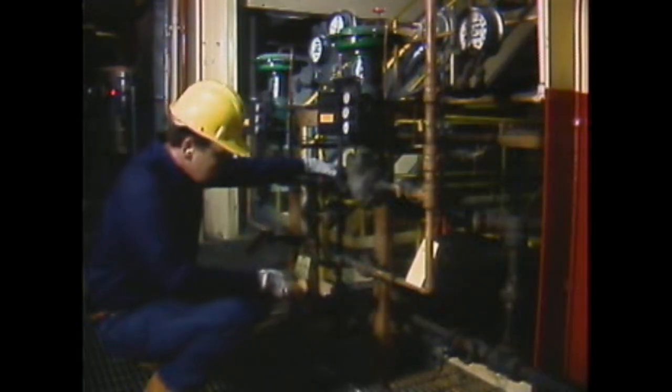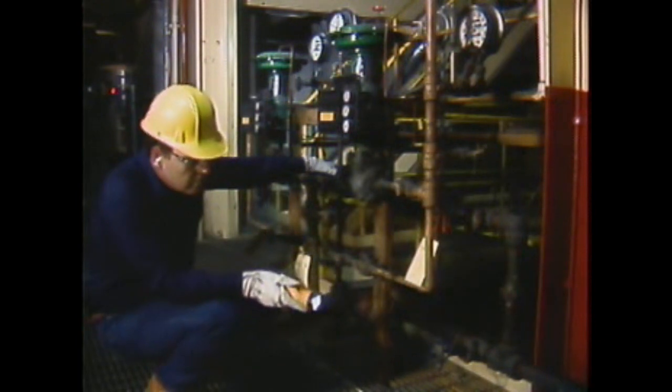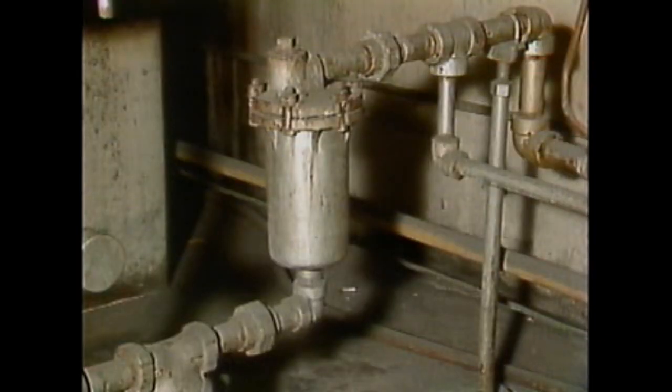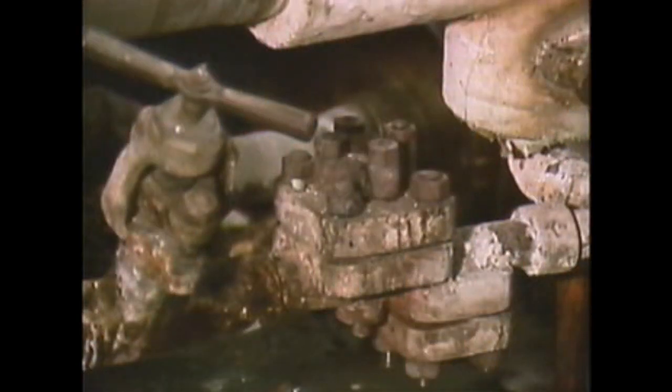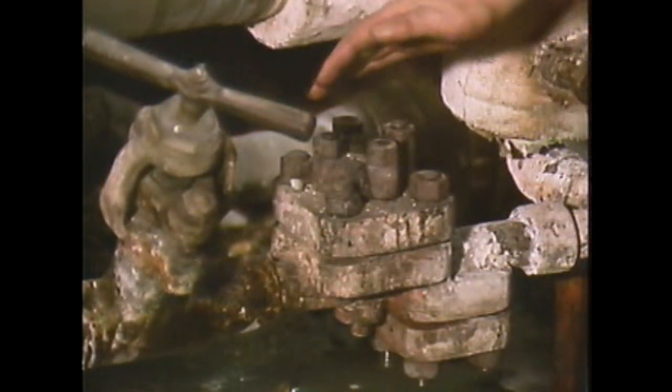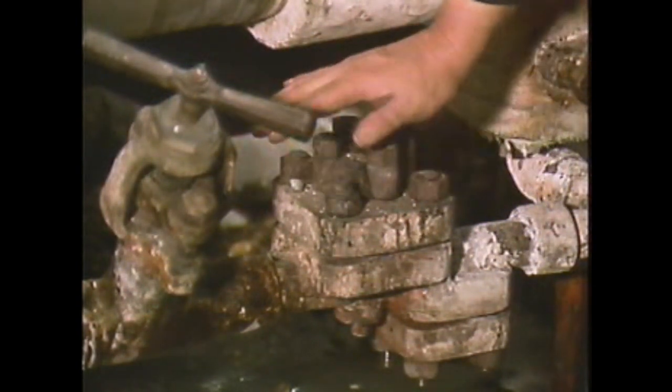Part of your job as an operator is to monitor steam traps and make sure they're operating properly. One important thing to check for when you're monitoring a steam trap is leakage out of the trap and associated piping. Typical places where you might find leaks are at piping connections and at points where parts of the trap's body are joined together. Another typical operator check is the trap's temperature.